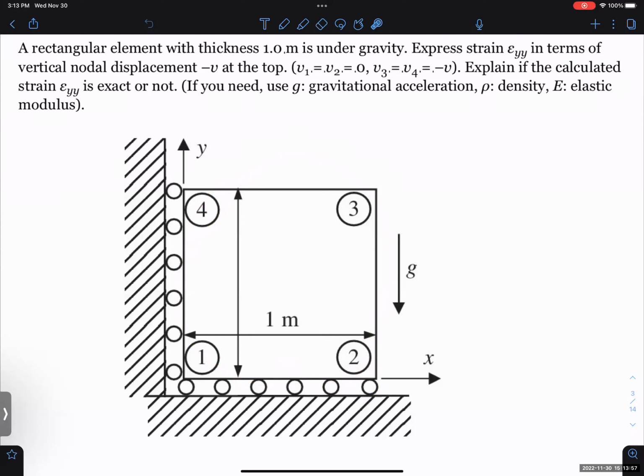The stress is caused by the weight of the paper above that specific paper, so the weight here is the largest. When I gradually move upward, the weight of paper above gradually and linearly reduces. And when it reaches the top surface, there's no paper on top of it, so the stress becomes 0.